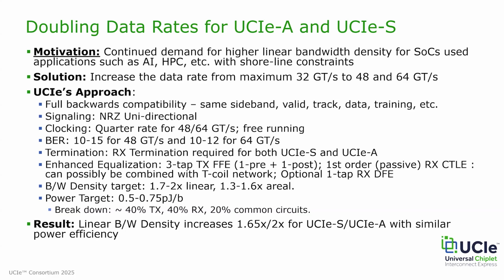It's a critical consideration for us as it ensures that existing systems, existing infrastructure, can seamlessly integrate with the new standard. And it provides a smooth transition path for system designers and developers. And also it ensures interoperability with older chiplets that are designed to the prior generations of the specifications, and they might have their own cadence of making changes to their interfaces. So as a result, we made no changes to sideband, valid, track, data, training, signaling protocol, bump map, those sets of things.